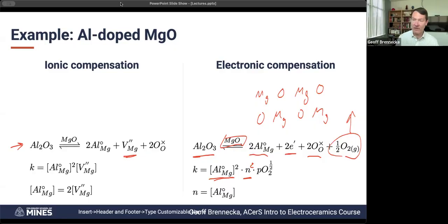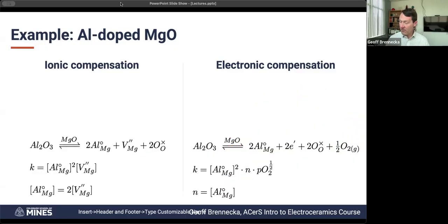If you remember chemistry, again, we've got Le Chatelier's principle. So that means that if we put extra oxygen into the atmosphere, that's going to push the reaction back that way because there's too much of this product and it's going to push the reaction to go in reverse. In that case, that would be precipitating out aluminum oxide. If we remove oxygen from the atmosphere and lower the overall partial pressure, that's going to push the reaction this direction and lead it to happen more easily.